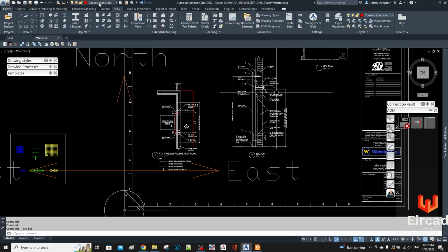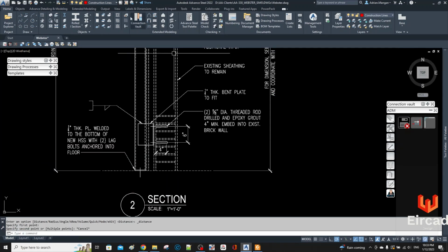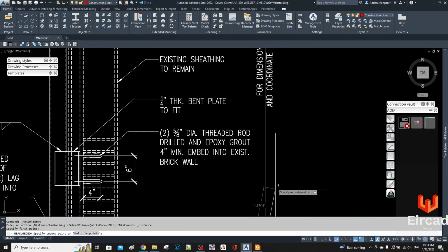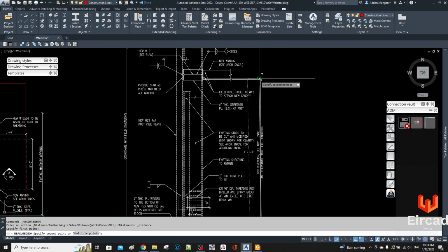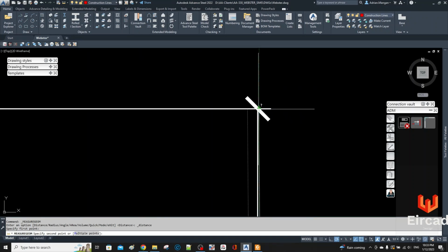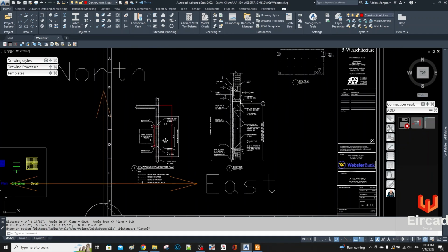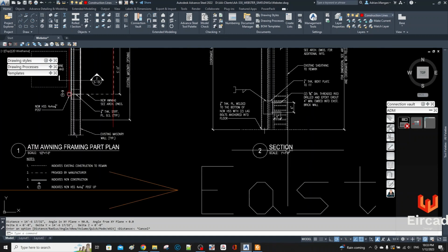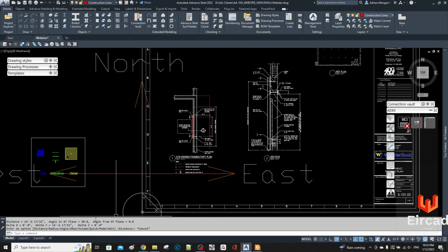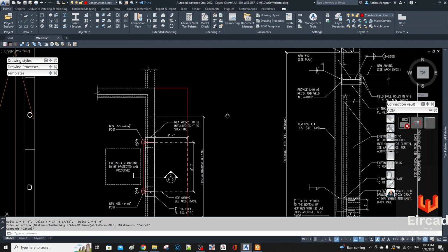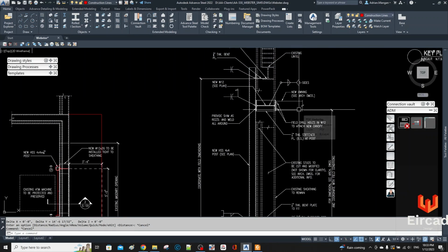Alright, so they're given a height here. Let's just check on the scale what the height looks like. I'll just go from the end of that line. 14'6". So this is a different scale, is it? Yeah, so this is 1:1. So 14'6", so 7'3". I'll put up that beam at 7'3".